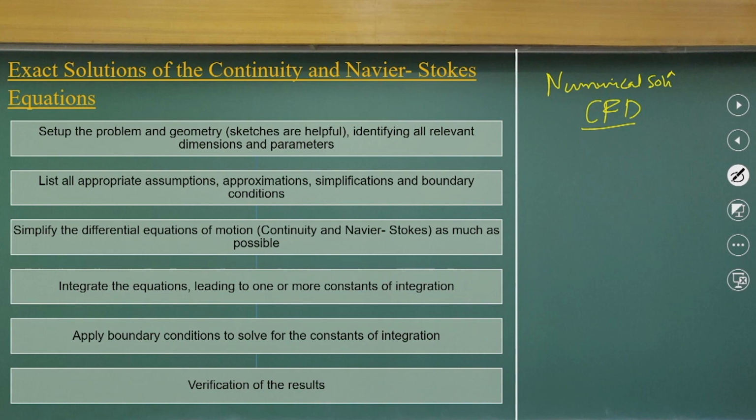So, if you use the numerical solutions of CFD for these Navier-Stokes equations, I will get the approximate solutions of U, V, W. This is what I am designating. These are the approximate solutions. Okay, the density and the pressures. Okay, these are not exact solutions. These are approximate solutions. More details you will get when you learn computational fluid dynamics, but we get the approximate solutions. But technically, many times we should simplify these Navier-Stokes equations, as we are discussing, that we should simplify the Navier-Stokes equations.